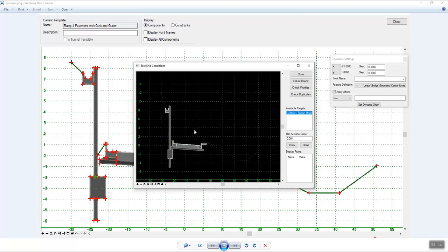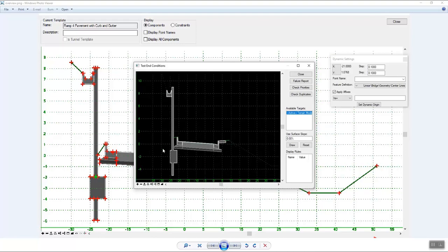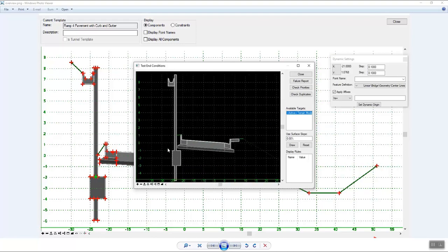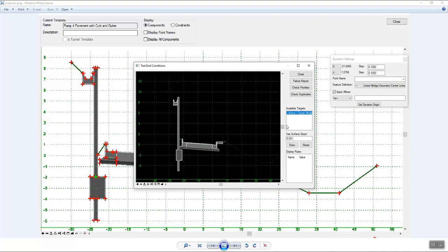Once you run the test, you don't have any issues. See what it looks like through here. If we go out and take a look at the active ground, hit the draw button, the gutter over there on the left hand side moves with the existing ground. Okay, and then we've got fill slope. Typically you're going to have a ditch for most all of this.